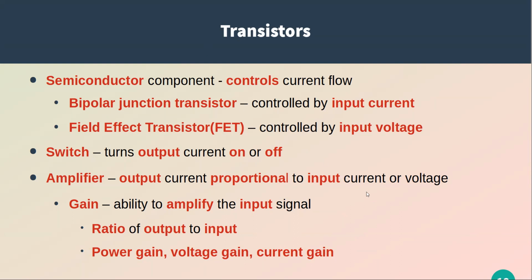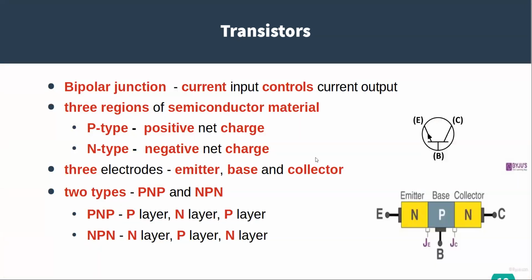We also can talk about voltage gain. It can be set up as strictly a voltage amplifier as opposed to amplifying current, or just as a current amplifier. There's different configurations of whether it's a common emitter or a common collector or a common base. And the same thing is true for field effects, different configurations, and they behave differently.